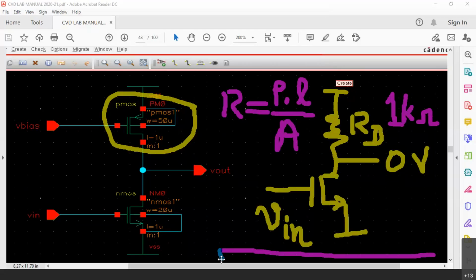You should have such area reserved. Now, L, length is there. Area of cross section, A is there. Rho is the resistivity of the material. Whether you use it as a N implant or a P sub or whichever particular layer is selected for manufacturing resistor.